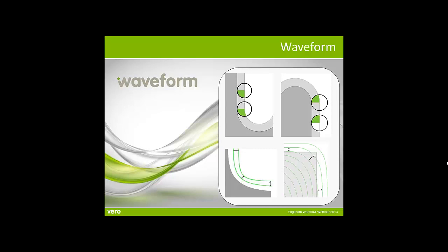And often people ask, is this the same as trochoidal? Our view is trochoidal paths are put into a toolpath to fix problems. Waveform actually went back to the genesis of the toolpath creation such that we don't need trochoidal moves.